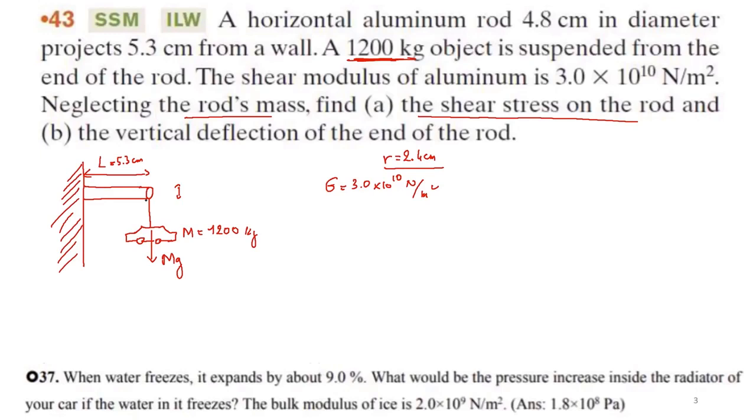Okay, now here, of course, the force that I'm applying here, F in magnitude, is just mg, because basically I have a static equilibrium. And this force here is a shearing force. The stress is a shearing stress. Why? Because the force is perpendicular to the cross-sectional area here. Sorry, not perpendicular, parallel. So this force is parallel to this cross-sectional area, so it's a shearing force.